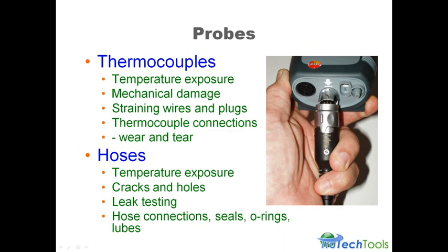And if it doesn't go down to 0, if you're getting oxygen in there, that means you've got a leak in your probe or in your connection, your analyzer, and you're sucking in oxygen. It's diluting your flue gas sample. So it's an easy way to test for that. If you don't, send it to us for a calibration verification, and we can test that for you.